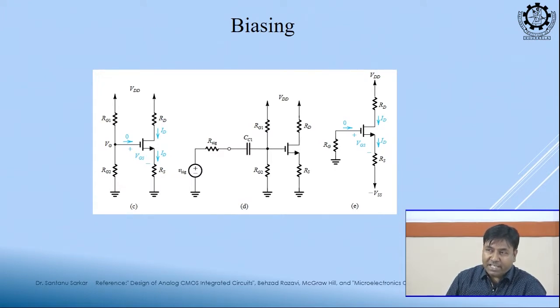Which kind of biasing is this? Potential divider. Okay. We discussed different biasing techniques already, so I am not repeating those, you can follow the old class. How many different biasing techniques are there? What is this? Coupling capacitor. Purpose? To connect the AC signal, but not to disturb the DC biasing. Okay. Rest of the things are the same.